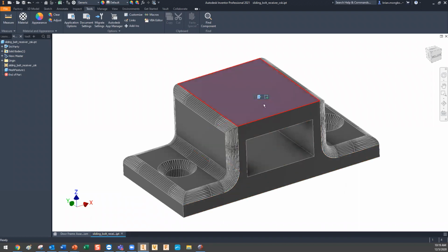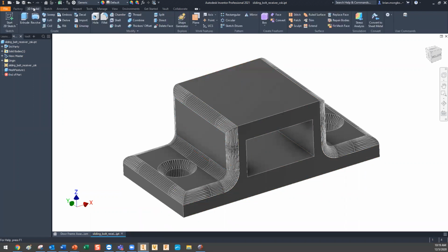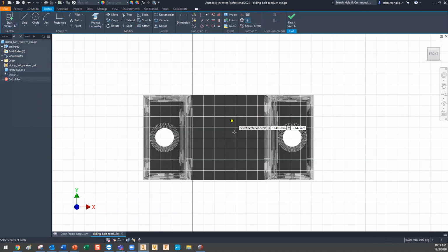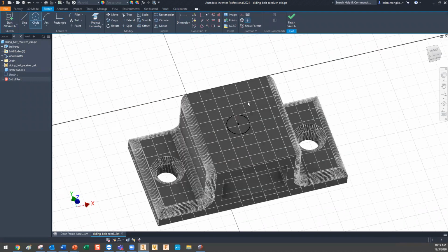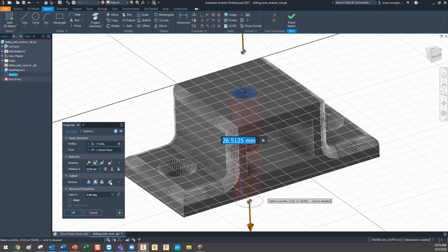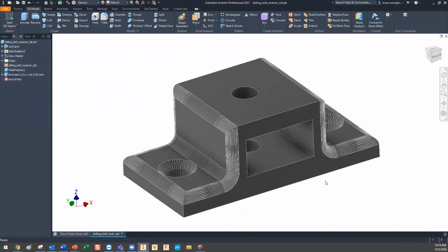You can see that the two triangles at the top went away. The two on here went away. Some of these still remain, but now this is something that's editable and detectable by Inventor. So for example, just a quick example here, I can create a little cut that goes through my model, whereas before it wouldn't detect it and it couldn't cut through those meshes like I am doing there.